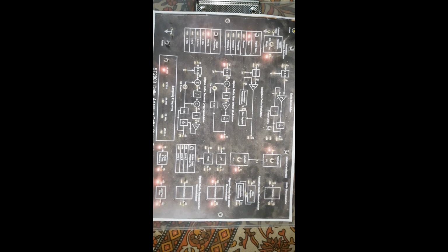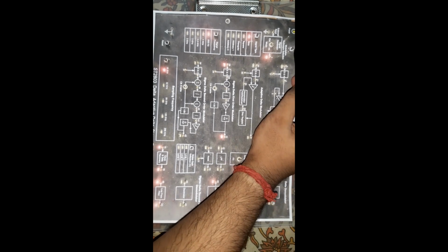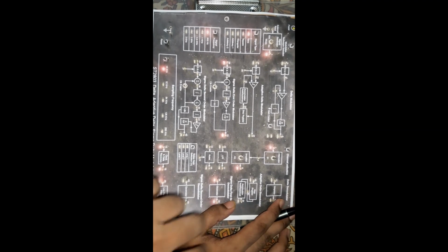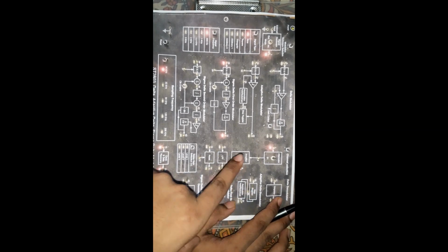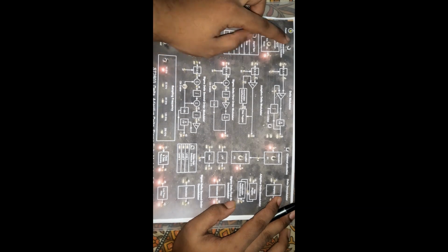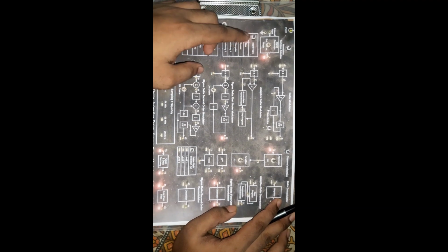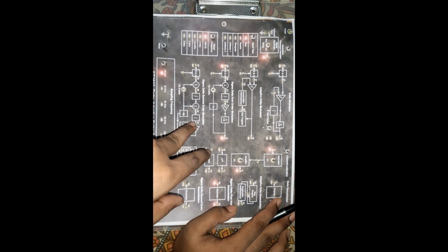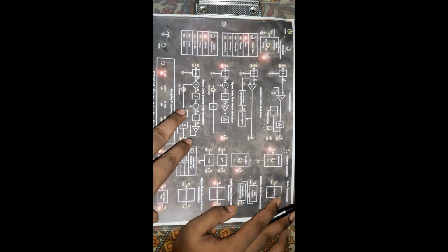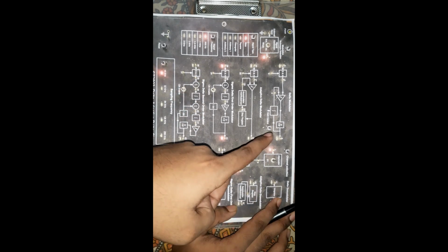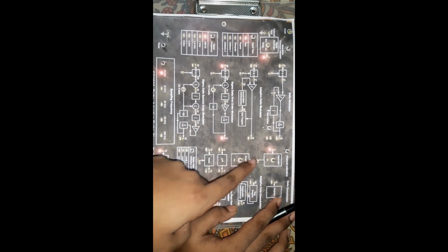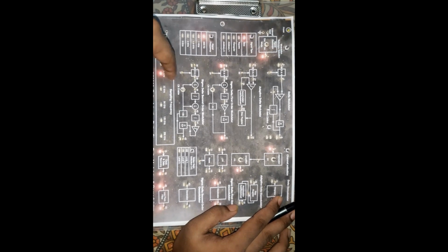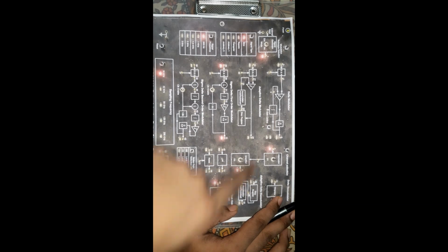Okay. Now there is a switch, that is the modulation technique selection. Whatever modulation you have to do, you can perform 4 types of modulation in this trainer kit. Using this switch, momentarily you can select and switch between these 4 types of modulation. That means whenever delta modulation is required, just by pushing this switch, you have to select the delta modulation block.